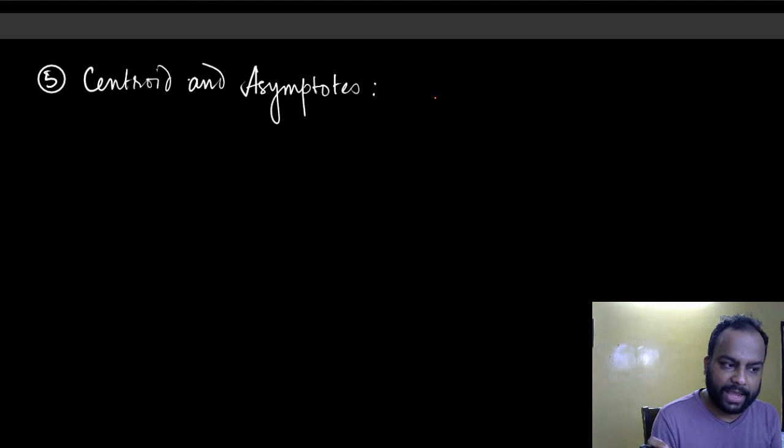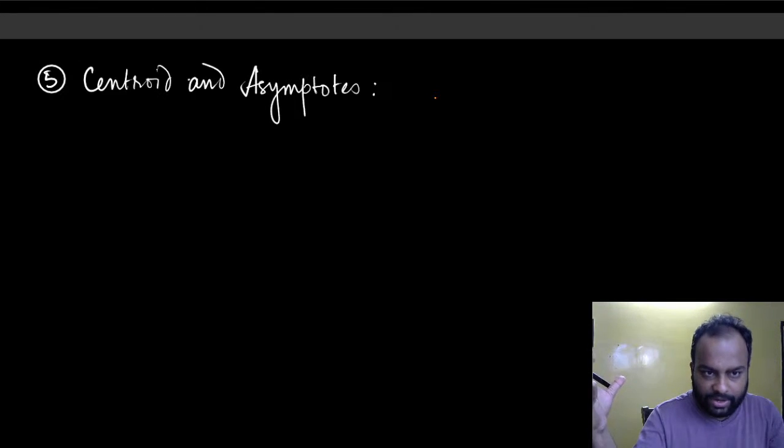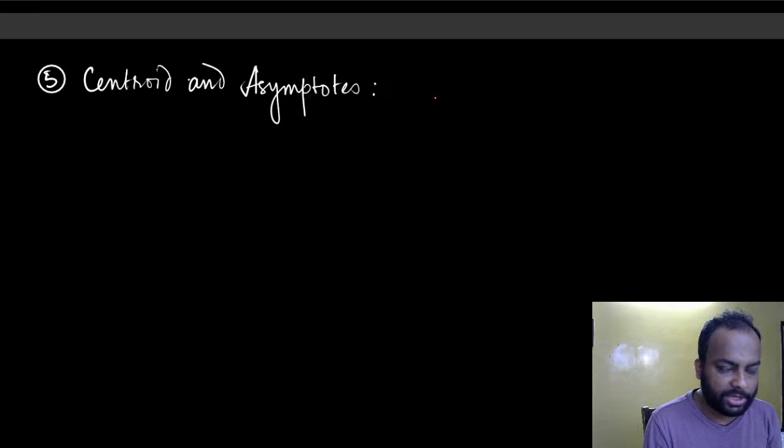Do you understand what I'm saying? I'm saying that when the gain becomes pretty large, then the curves essentially go to infinity. The roots essentially go to infinity if there are no zeros. We shall later on see transfer functions that have finite open loop zeros, and for those situations the result would be slightly different, right? But for right now, we are going to only talk about transfer functions that do not have finite open loop zeros. For them, the roots would follow the asymptotes.